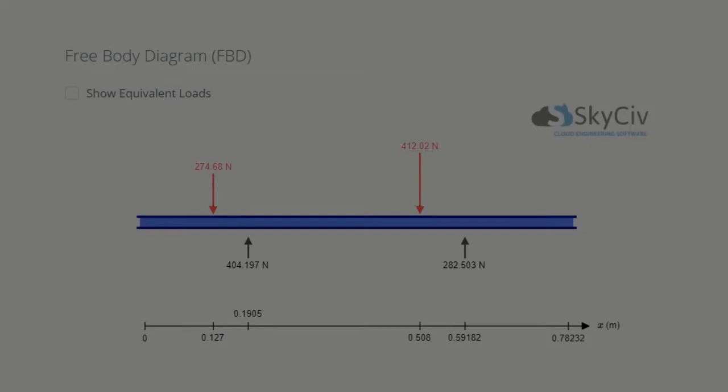So this is our free body diagram. So what we actually have is these two, which are the person's front foot and the person's back foot, and these are two wheels and their reaction forces. What we actually used was 70 kgs for the person, which is about an average weight, and then we managed to convert it to newtons, which is about 690 newtons, and then we have our front foot and our back foot with those forces distributed. So overall length of the skateboard is about 0.78 meters, about 78 centimeters. That's the average professional full-size skateboard.